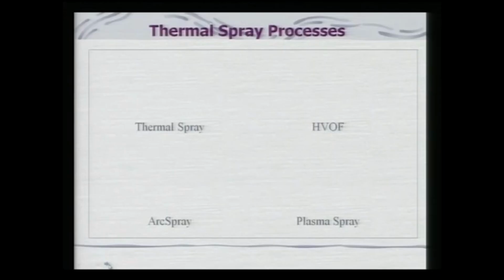So, in thermal spraying, we have either a solid billet or maybe some powder feedstock that is basically being heated up first. Once it is heated, it becomes a molten droplet. Those are now accelerated via a carrier gas, and then they impact on a very rough surface. So, we have a mechanically rough surface, and then these particles start getting deposited onto the rough surface as what we call splats. So, we had a roughened surface, and then we can see the deposition of this material.